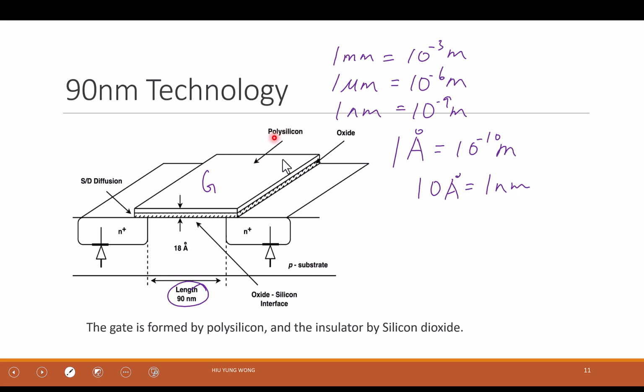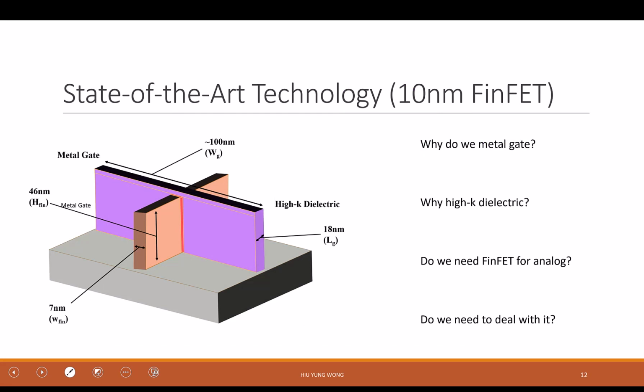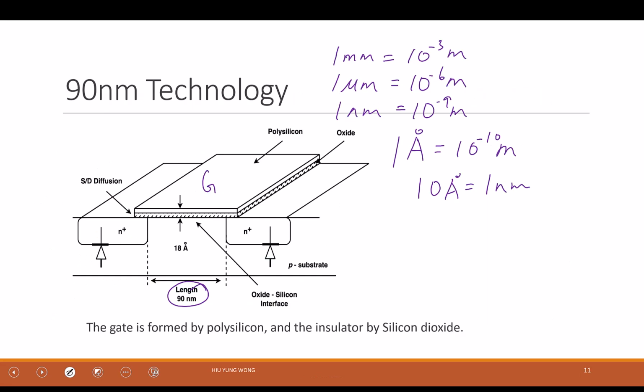And for the gates, we use something called polysilicon. It is just silicon, but not crystalline, it is polycrystalline, and very conductive. However, when we come to the so-called FinFET, for example, in this case, it's no longer state of the art, right? We have even more advanced nanowires, but we become something called a 3D transistor. So let's take a look at what it looks like. Instead of this so-called planar structure, this is planar, and you expect the electrons will flow on the surface from left to right, right? Electrons from left to right, but current from right to left, if this is source and this is drain.